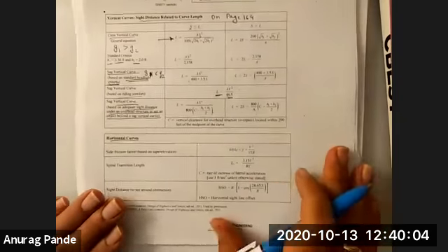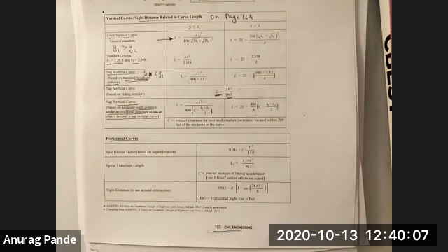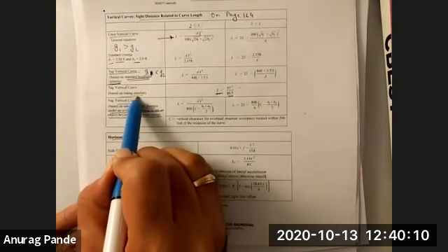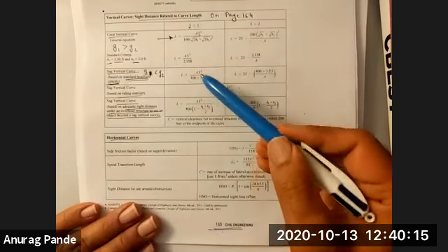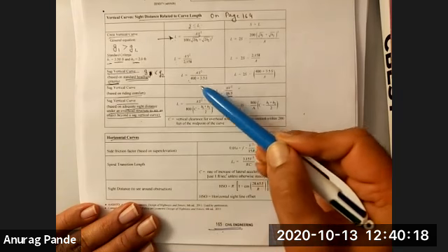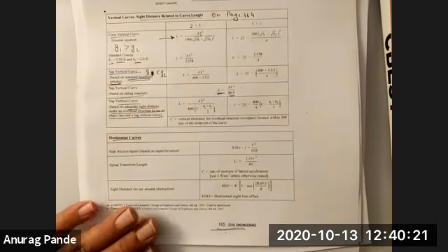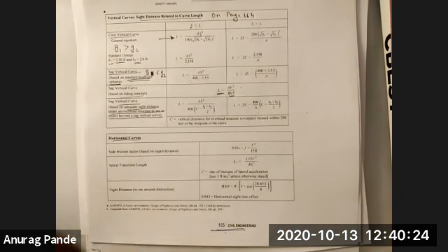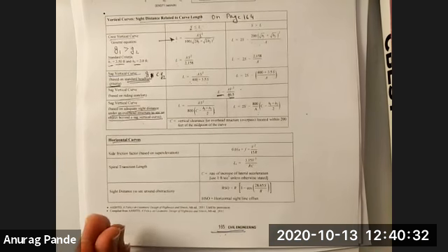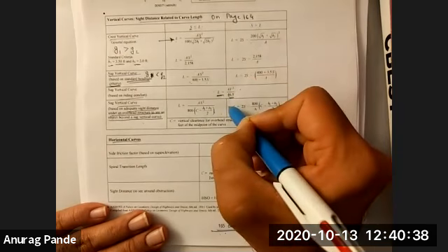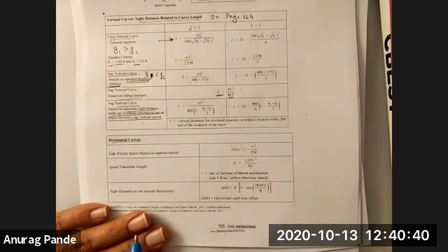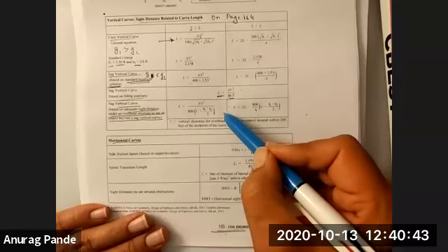So what you're seeing here is that on a crest vertical curve, only the hill could block the view. But in a sag vertical curve, three different criteria might present you a problem, so you might find a minimum value of length based on three different formulas. How do you choose between them? You apply all of those formulas and make sure that you provide the maximum possible length from those formulas. All of these formulas give you the minimum required length, and whichever gives you the highest value, you use that length for your design, because that will address all three of the criteria.